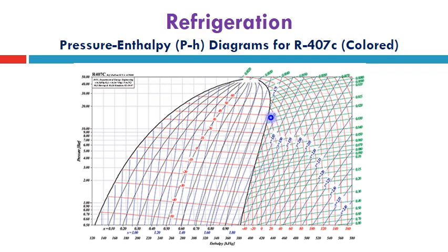And it can also be read from here easily inside the superheating zone to estimate the compressor performance and the isentropic efficiency value, and the deviation from the isentropic compression process if listed in any problem.